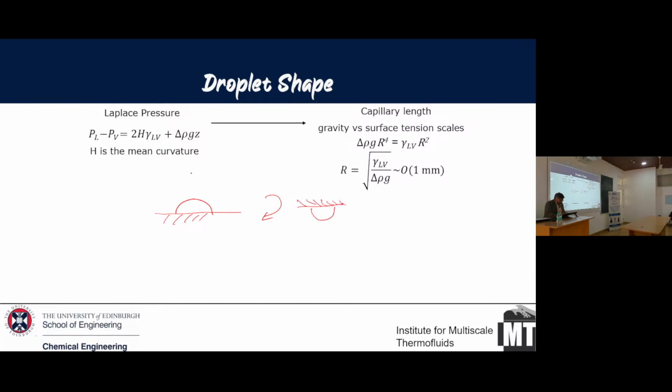Now, if the diameter of the droplet is less than the capillary length, we just assume that it is not affected by gravity. Actually, it is incorrect. It is affected by gravity. It may be affected by gravity in more ways than none. In fact, when we do evaporation, we don't use capillary length as an immediate cutoff between what is affected by gravity and what is not.